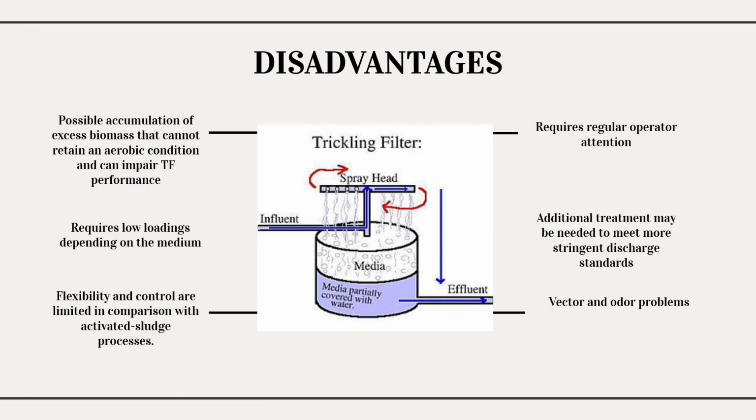Other than that, another disadvantage of trickling filters is the high maintenance cost of the rotary distributor center mechanisms. So for any maintenance service of the rotary distribution mechanism, it would require a complete removal of the rotary distributor mechanism, guide rod and arms.